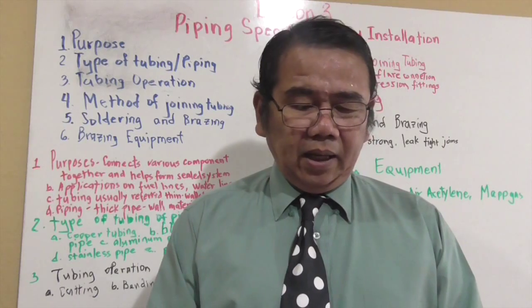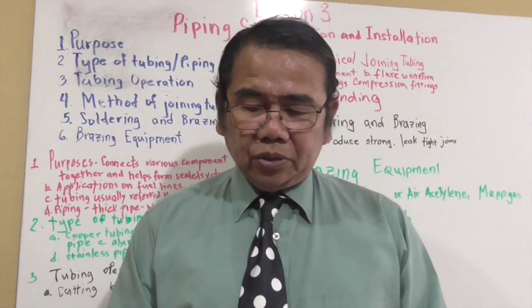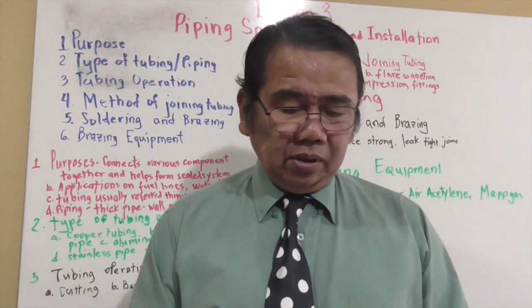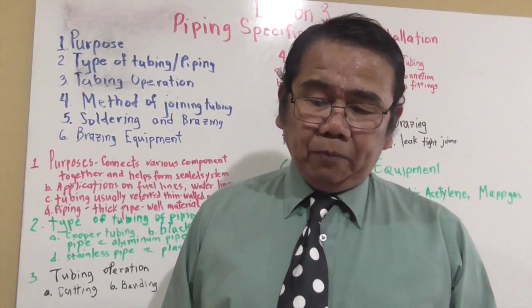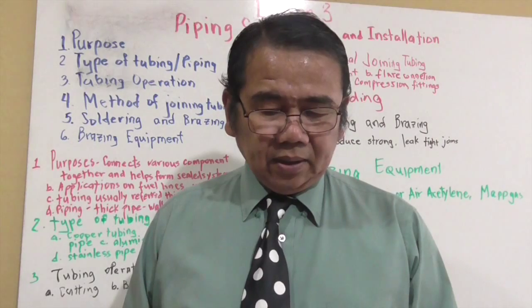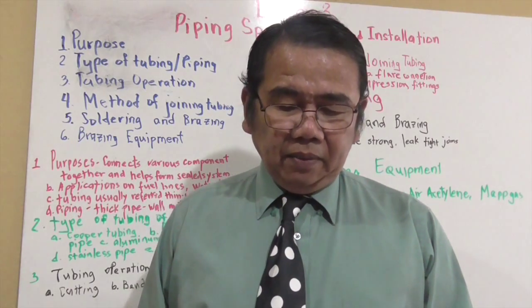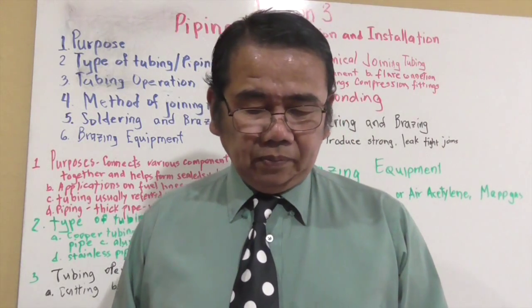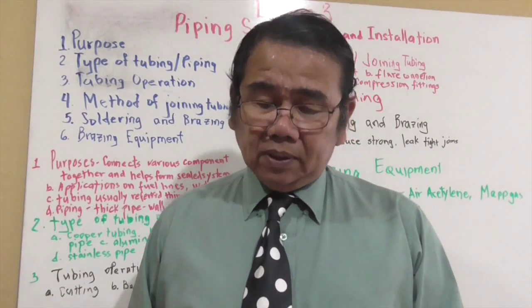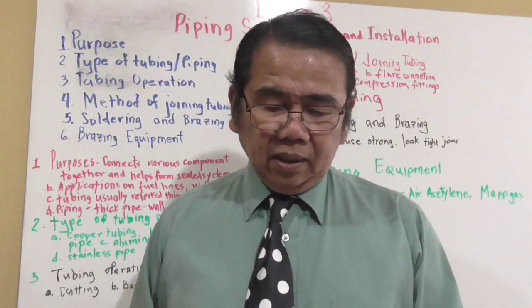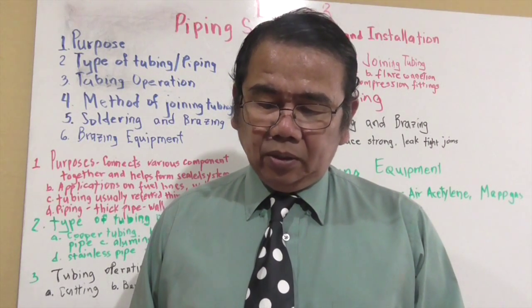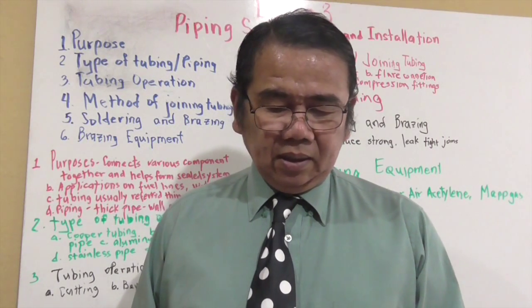And then heating and blowing low temperature silver solder, continued. Heat the tube 1.5 inch to 1 inch away from the end of the fitting. Heat evenly all the way around the tube. When the flux on the tube adjacent to the joint is melted to a clear liquid, transfer heat to the fitting.